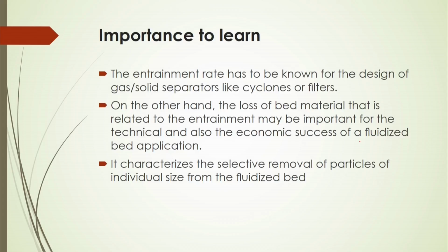Now, the entrainment rates have to be known for the design of gas solid separation equipment, like cyclones or filters. You have to know the entrainment rate before designing the gas liquid solid or gas solid fluidized bed. On the other hand, the loss of bed material related to the entrainment may be important for the technical and also the economic success of the fluidized bed application. Sometimes you will see some materials lost because of these entrainment characteristics.